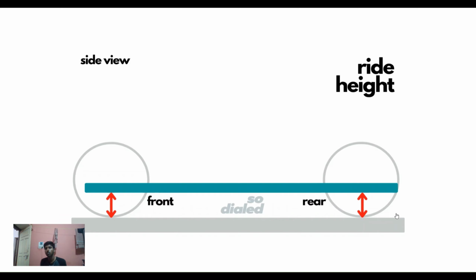The cons of having lower chassis height is that there is less room for the wheels to travel. So the suspension travel is not being used effectively if you have lower chassis height, and it will become more of a rough ride. Each and every bump will be felt more acutely. You can feel it more sharply. That's the whole point when you have lower chassis height.